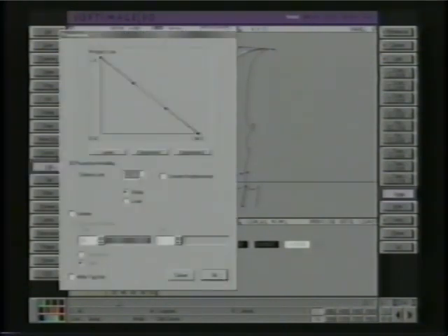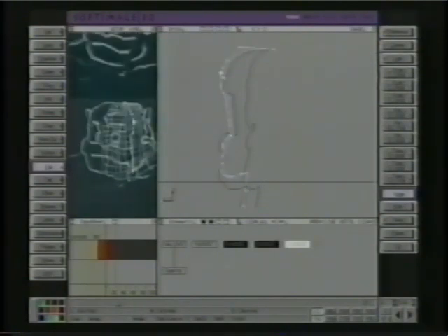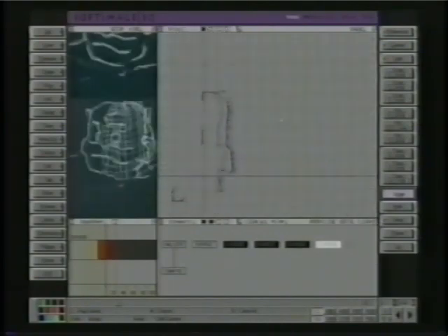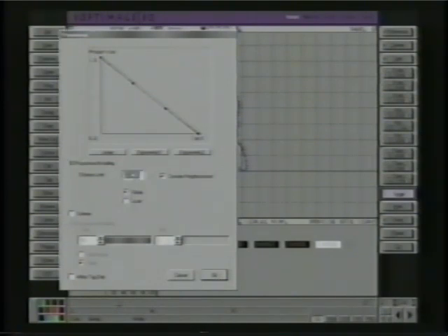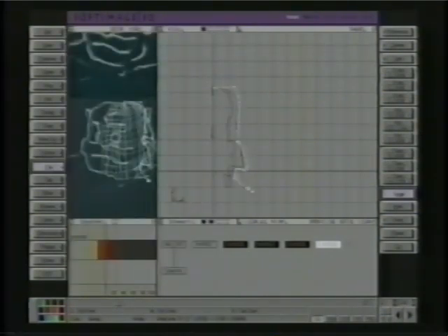If you use proportional modeling with curves, you want to turn on the consider neighborhood. Let's turn this down a bit to 1.4. Now this next curve, it's basically the side of his head, so it's going to be quite a bit different. We're going to need to move quite a bit of points. Let's see. We'll still use proportional modeling. Linear is good for this kind of work because you want it to straighten out. If you keep pulling the points back and forth, they'll straighten because of the linear. If I had a smooth fall off at the top, then it would be difficult to work this out with the same ease.